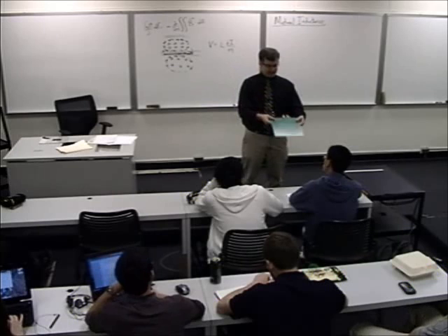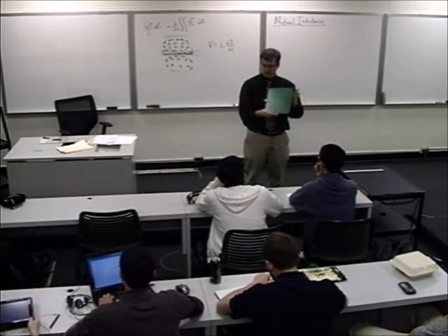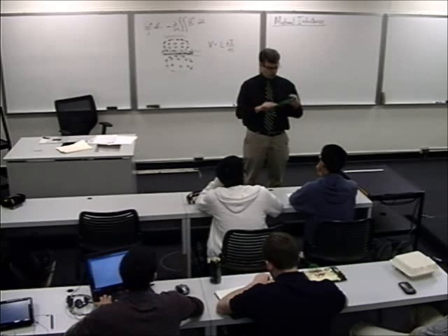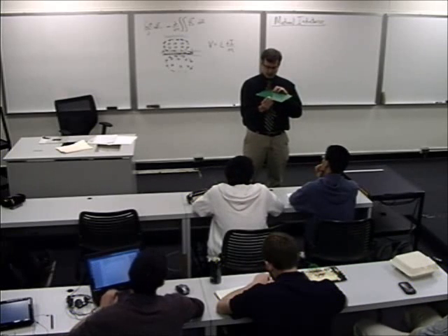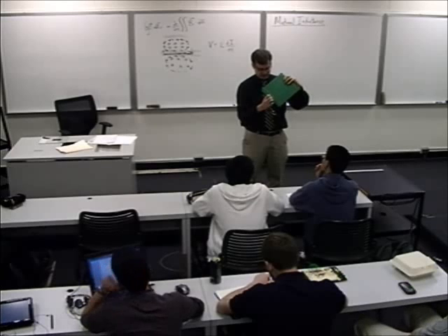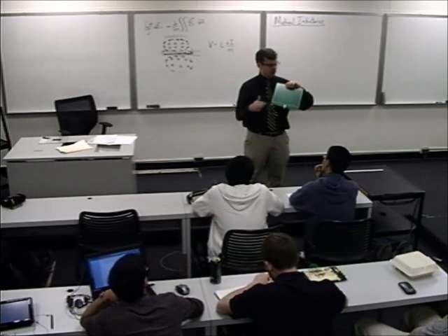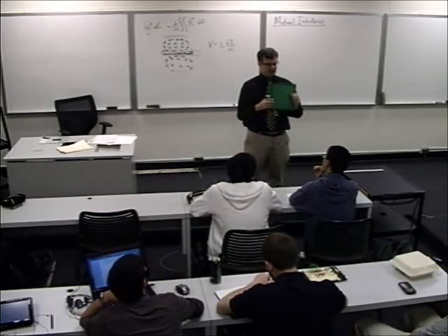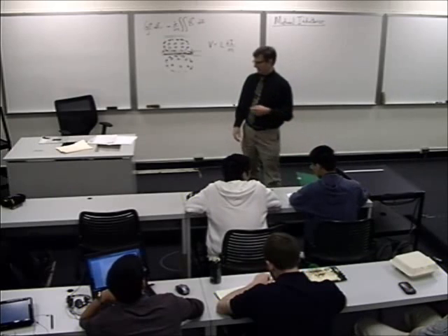So I'll just go ahead and pass this around so that you can understand the geometry that we're talking about. This is just cheap FR4 circuit board. You can see the conductive path that goes all the way around. And this thing is a BNC connector, so you can connect it to a coaxial cable. That little twisty thing in there, the little yellow thing at the base, is actually a variable capacitor to help tune out the self-inductance. We'll see later why that's important in this kind of system. But this is basically the gist of it. I'll go ahead and pass it around. You can take a look at it.